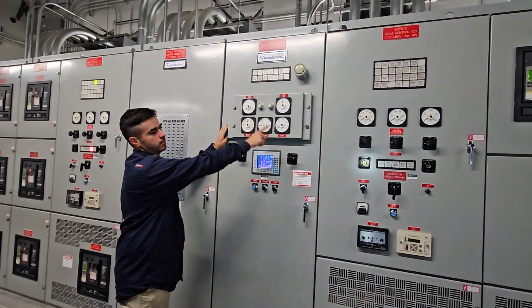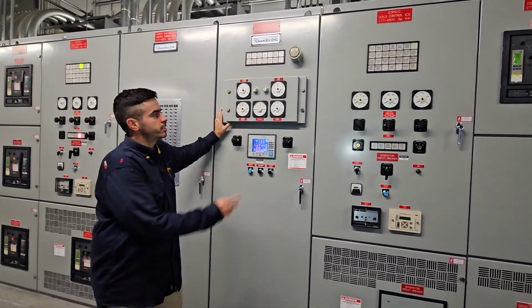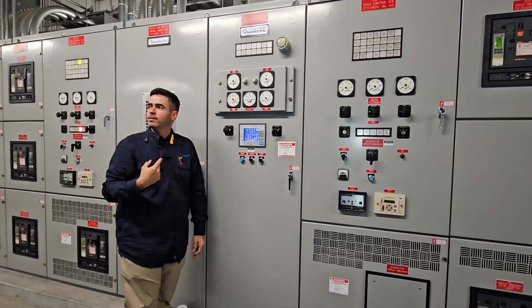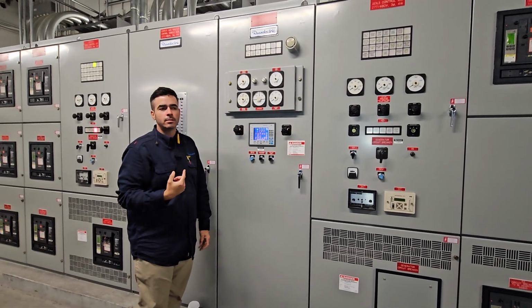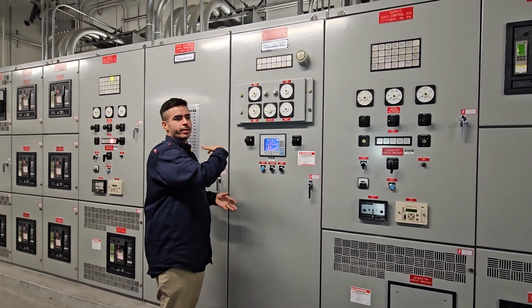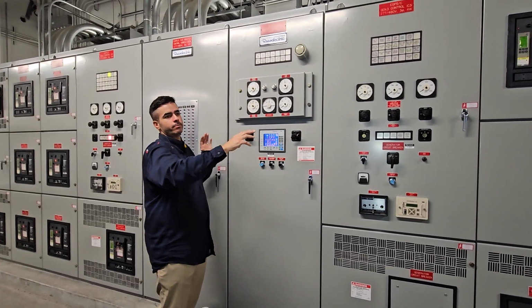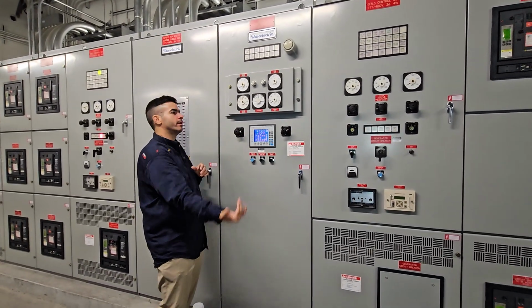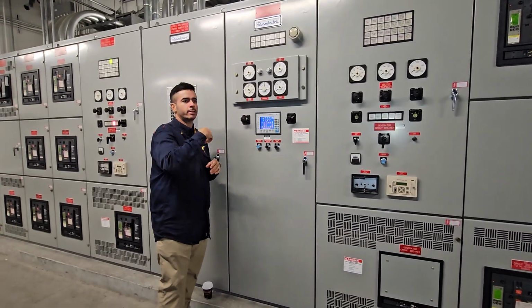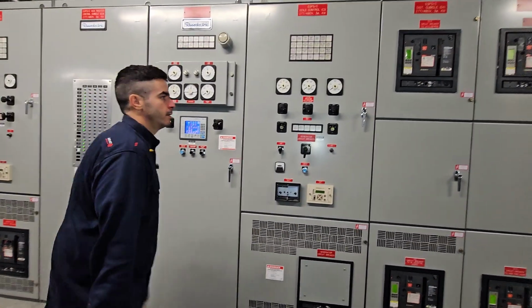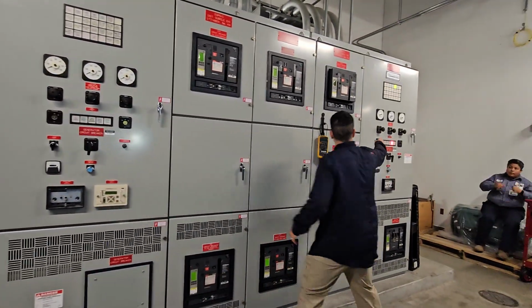12 o'clock, close it. You see how in this case it was going backwards? You know why? It's automatic and does what it wants, because it's driving it, right? So regardless of the frequency, we're at 60.1, the system says, hey, no, lower the frequency and come back because I need you as soon as possible, right? Same thing over here. I want to see how quick the other one is to sync.